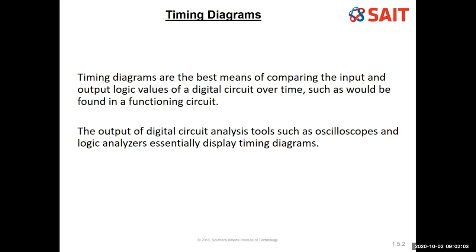I'll often connect things up to an oscilloscope to analyze and to see what's going on. So timing diagrams are a very important tool to analyze or predict what will happen in a circuit, or do troubleshooting.